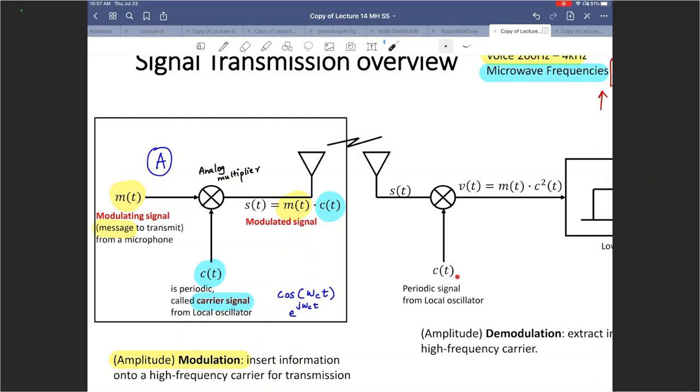All you need to know is the frequency. So to match in terms of a frequency is pretty easy. However, in order to match with the phase, it is very, very difficult. So actually we will revisit this topic of synchronization in phase of the local oscillators later on in the lecture. But it can have a very, very dramatic effect on the signal reception. In fact, for certain phases, you may receive nothing, absolutely zero. It might cancel out completely.